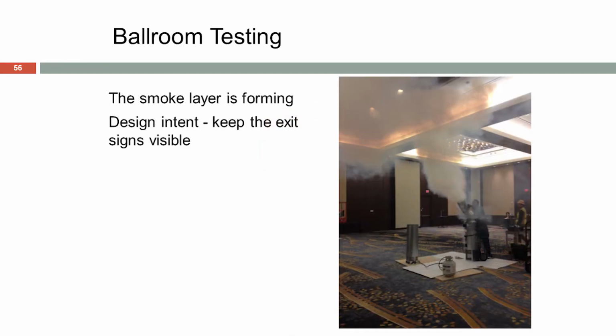Okay, so looking across the area here, we're seeing a general smoke layer building and dropping, and we're continuing to add smoke until everybody that has an opinion gets to see enough to sign off on what they're seeing. Again, I didn't stipulate how much smoke they wanted. I didn't stipulate what size energy fire we were simulating. They wanted to see their systems in operation. We gave them that opportunity.